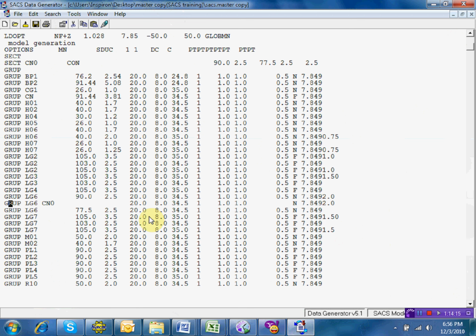Even this is quite sensitive. Even if you put this as 8, it's already an error. If you put this 8 and it's too small, you cannot tell 8 and G apart, they are almost the same. If you run, this is an error. It's very sensitive. That's why usually using the data gen, it's only load combination. Much faster to just copy and paste.